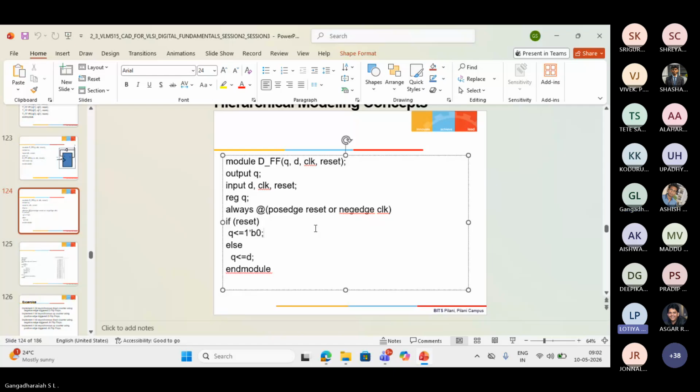If we do not define the sensitivity list, can we say that a sequential element will behave like a synchronous element? See, let us say if you have purely combinational logic, generally tools will support it if you put a star. It by default understands in some scenarios. There are some limitations there. Today's synthesis tools will understand that even though you do not mention all the signals which are really sensitive, they are all available and sitting inside the sensitivity list. But if you really don't want to take any risk, you can mention them, of course.